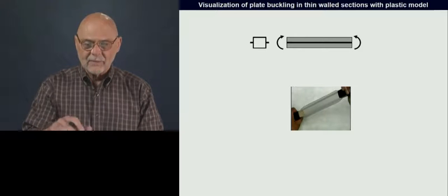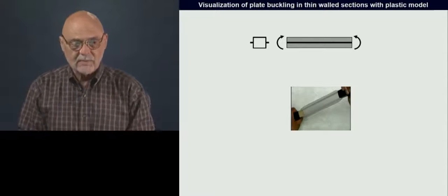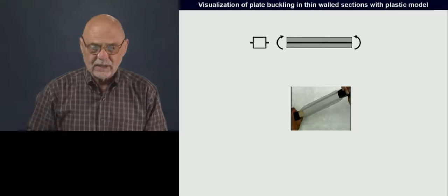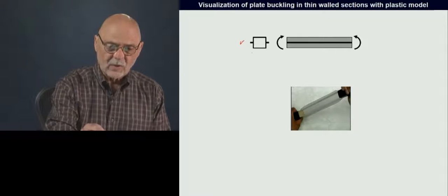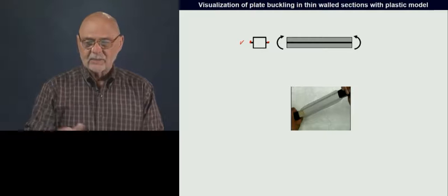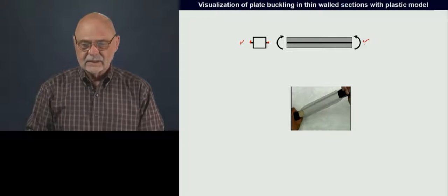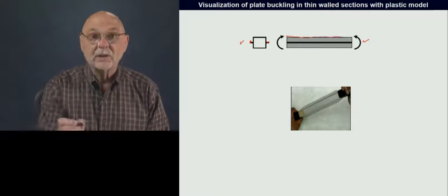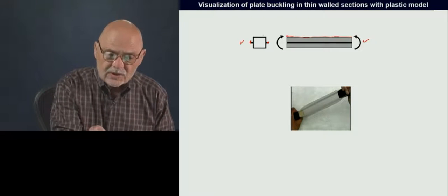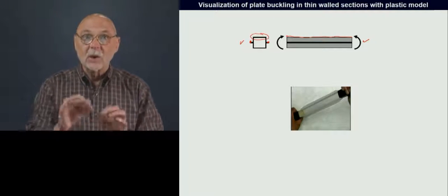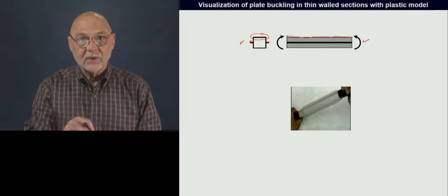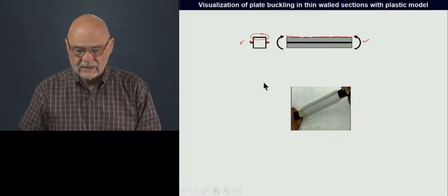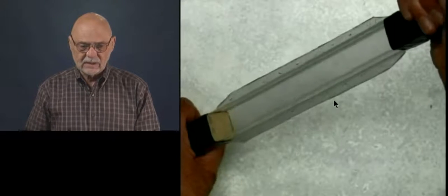And let's give an example of that so you have a feeling for what we're talking about with plate buckling. What you're going to see in this little video is a couple of hat sections that are welded together, and I'm putting a bending moment in this direction. So this top plate is going to be in compression. We're just going to consider this top plate, just one element of this very thin-walled beam, and you'll see it pop into this state of plate buckling right there.